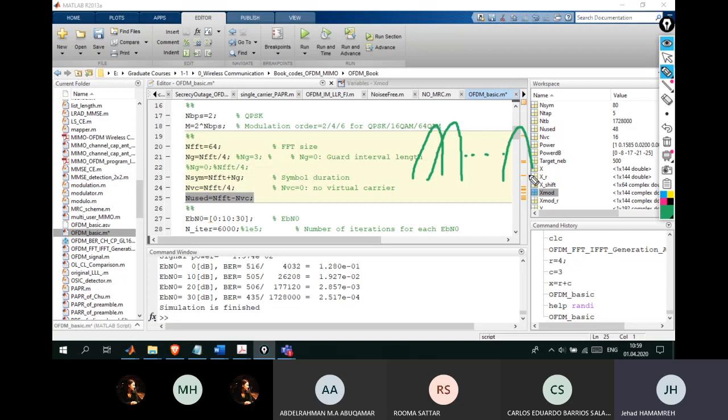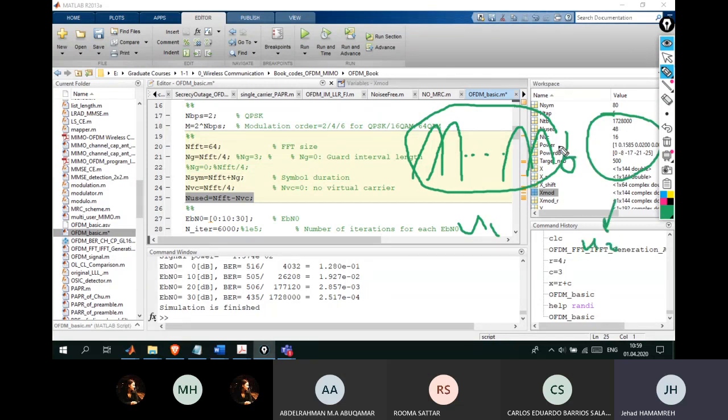If you take 64 and the other OFDM symbol adjacent to this one also takes 64, then you don't have any gap here. You are assigning this OFDM symbol to user 1, and the next one maybe to user 2. So you will create significant interference, because we know the sinc oscillates and has side lobes. To reduce this interference, the subcarriers at the edges of the OFDM, I just cancel them. I don't activate them. Before you deactivate, your out-of-band is something like this. Let's say these are the power spectral density at the edge of your OFDM symbol. But when you deactivate some of these subcarriers, your out-of-band becomes something like this.